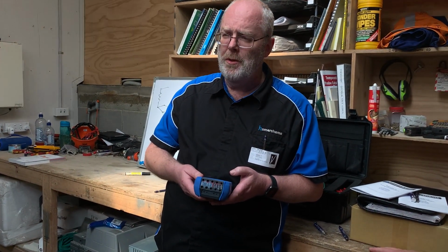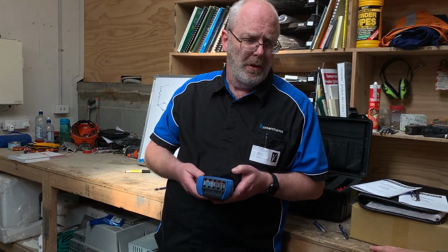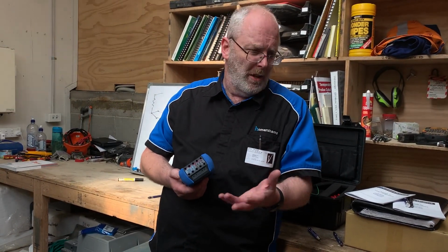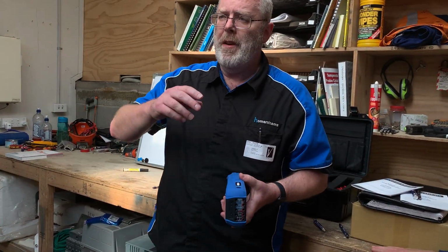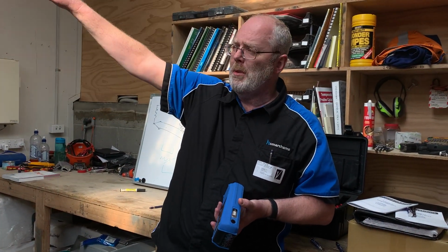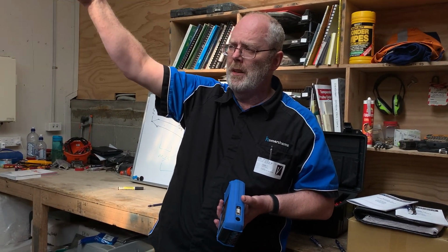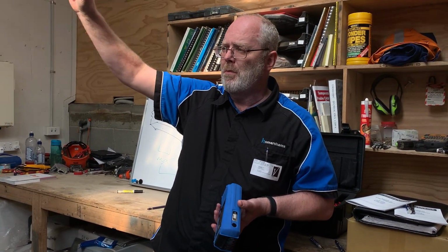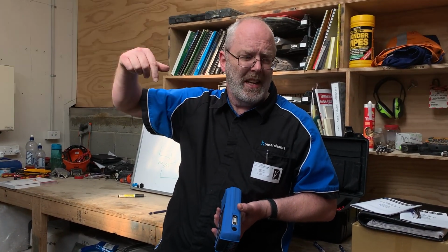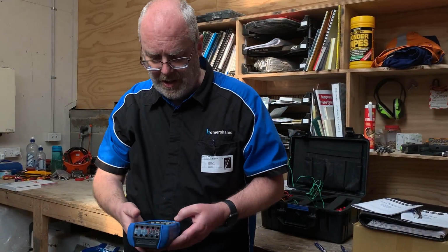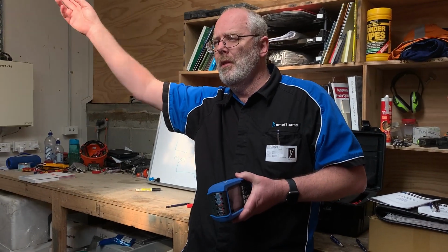It's got what I like to facetiously call apprentice mode. That's right, yeah. That is, you can set up tasks for someone who doesn't know as much. I call it apprentice mode, but it could be for anyone. So for example, if you had in the factory a whole lot of big digital displays up on the wall, 4 to 20 in, and they display a temperature from the process, and you want your tech to go and calibrate all of them. You can preset that as a task. And just say, go and perform task 1 on every one of those setups.